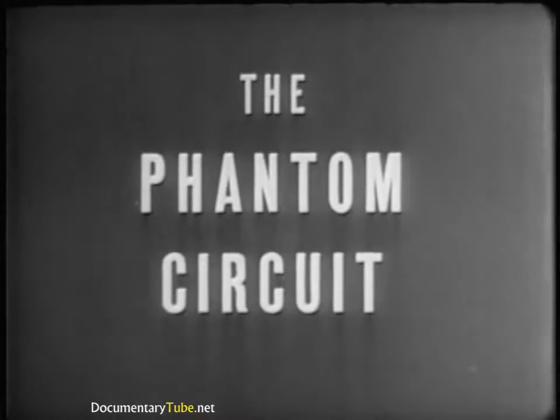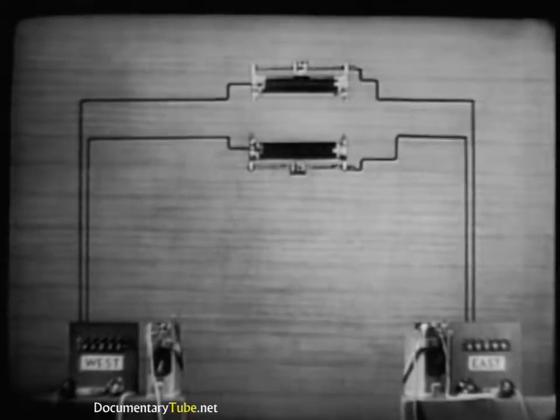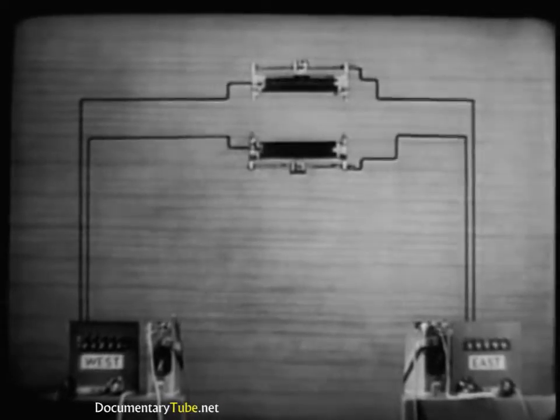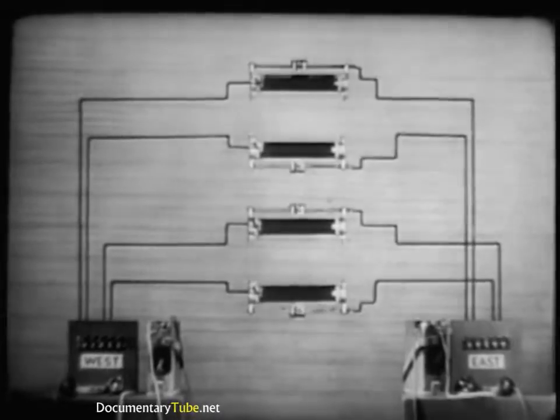There is another way to get a good extra channel cheaply and without the disadvantages of a ground return. This is to install a phantom circuit. The phantom is similar to the simplex. Instead of using the telephone circuit and the earth, however, it uses 2 telephone circuits.